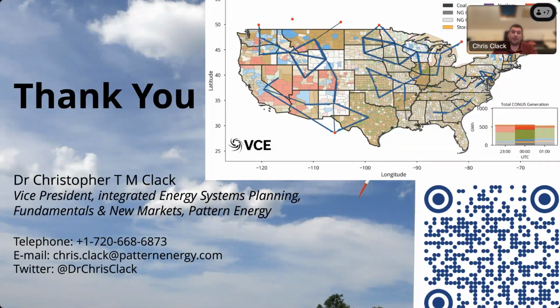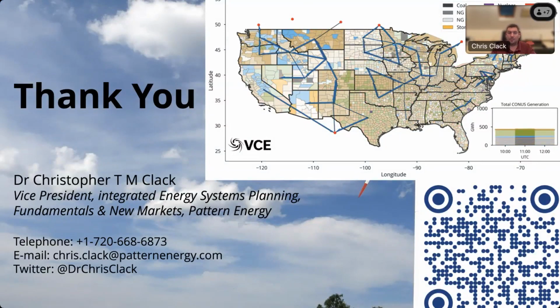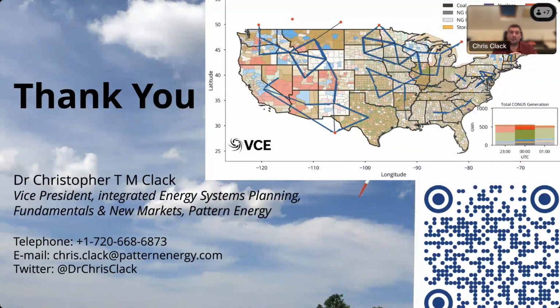But then we're thinking about the distribution interface, like the infrastructure, the wires, essentially the feeders, the substations that are having to deal with all that power that would be pushing in. If we're building more load, which is what we see happening, you can offset some of that increase in cost. But you can also plan ahead and use the distribution infrastructure to actually pass the power back to the transmission system. And so when you net out all those different costs, you end up with a slight cost benefit.